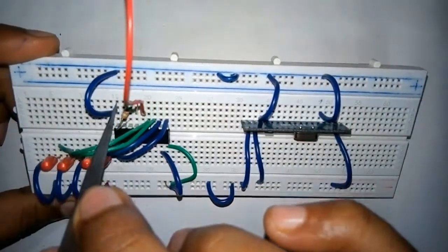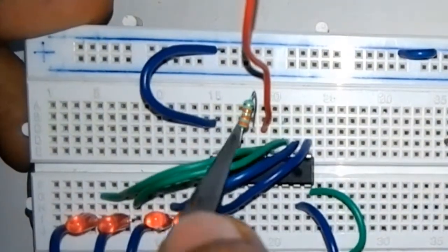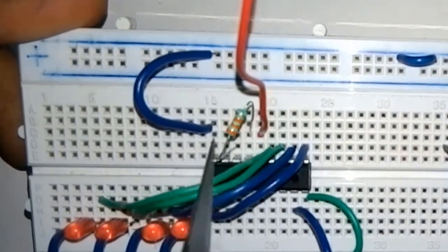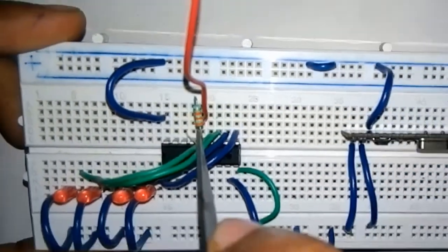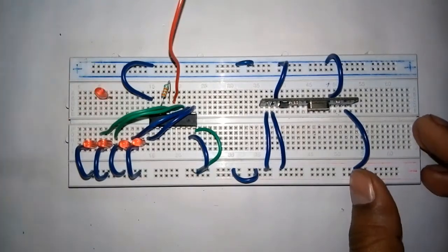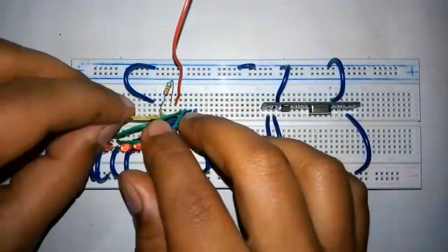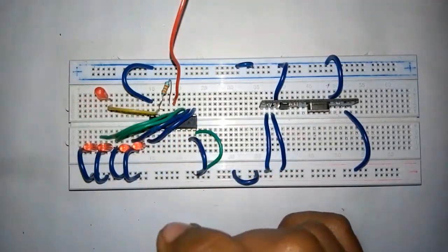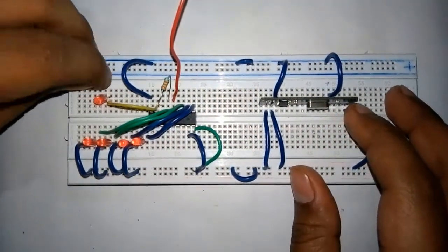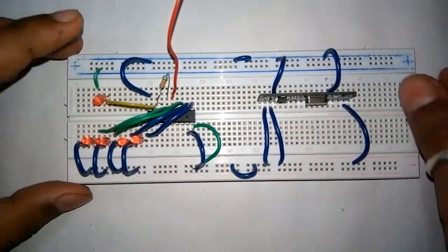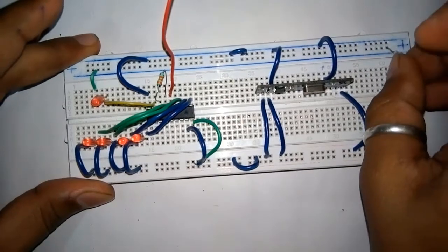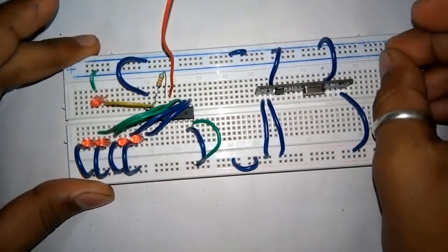Now there is one more, the 17th pin, which I have told you is the valid transmission. So I will place one more LED on the 17th pin. Actually this LED is used to show whether the transmission is on or not. When this LED is on, it means the transmission is going on. So I will connect this in the same manner. Positive leg to pin 17 and negative leg to the ground. Now I will connect this wire because I have to short the grounds.